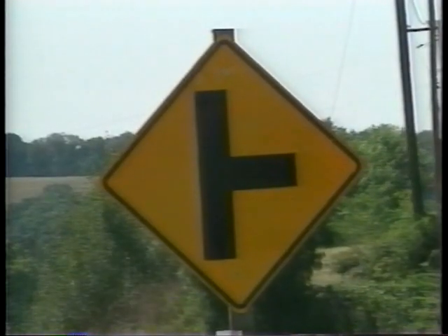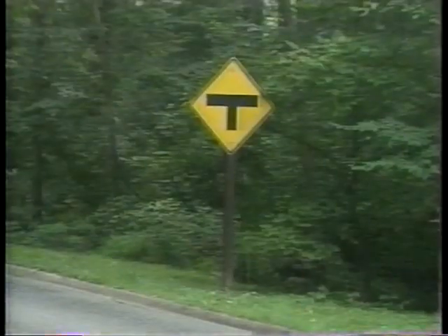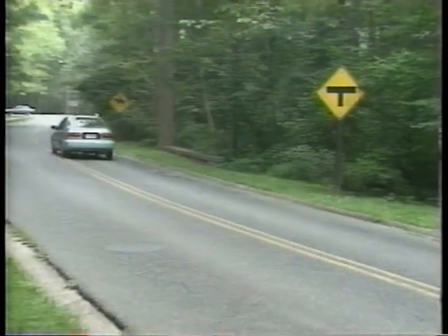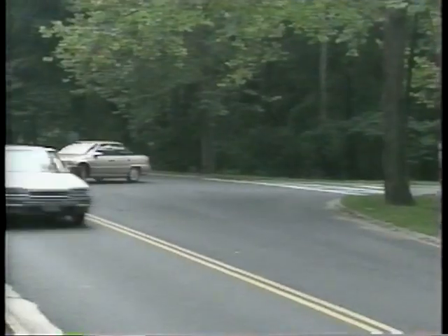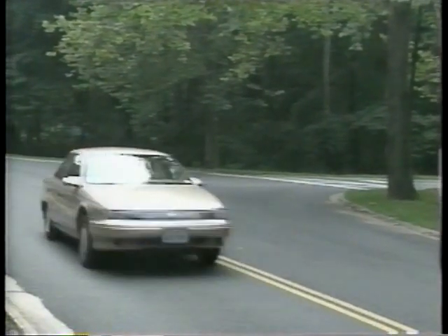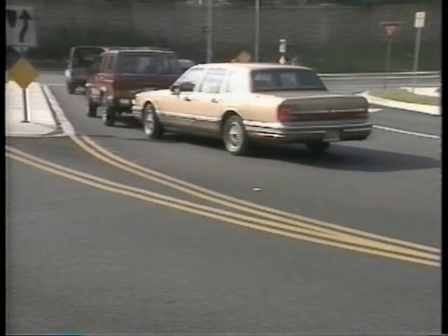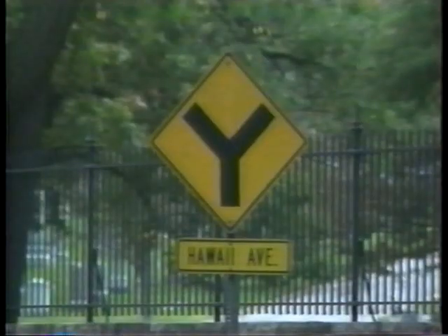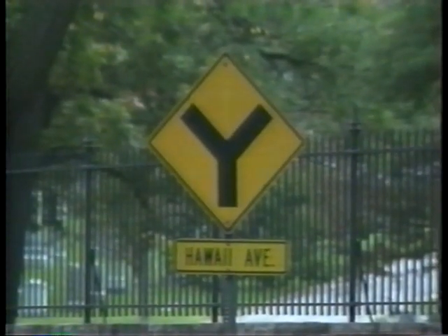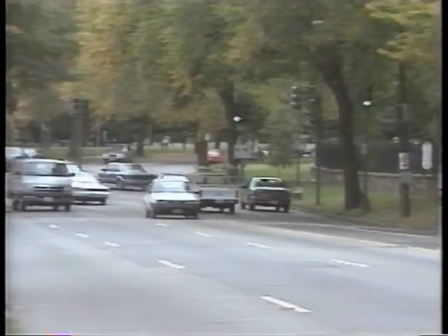A side road sign is used for the same reasons as the crossroad sign. The T symbol sign is used to warn drivers that they must make either a right or a left turn. It is used only when there is no stop before turning. It should not be used if the intersection is channelized, if there is junction signing, or if advanced turn arrows are present. A Y symbol sign is used for Y intersections. The same rules apply for this sign as for the T intersection sign.